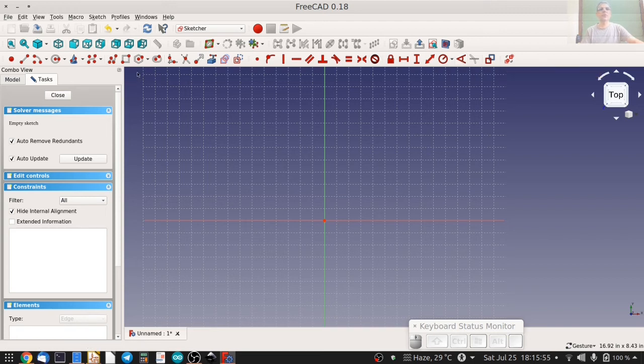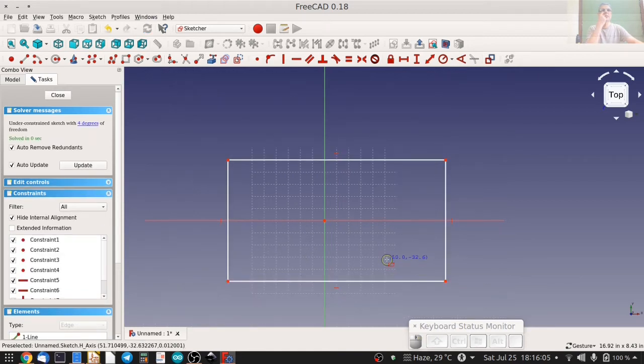So with that quick walkthrough, let's make a sketch. Here's the rectangle icon. Let me click once, drag, and place it here. So that's our rectangle, and it has 4 degrees of freedom: the width, the height, and the position of one of the vertices with respect to the origin 0, 0. Those are the 4 constraints that we need to fix before this becomes a fully constrained sketch.